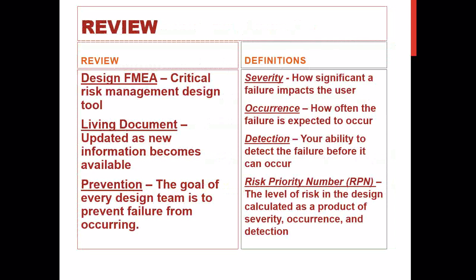And so we've got acceptably lower risk priority numbers. And that's the whole idea behind the FMEA: to put together for ourselves, as shown here, a list of recommended actions, our ability to document what actions we took, and what impact they had on improving the performance of the product and mitigating the risk.